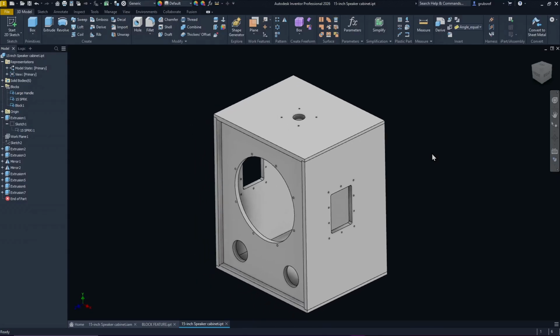And then you have the ability to take a sketch or capture something off something that does not have a sketch or has multiple sketches where you would spend way more time trying to recreate. So that's a simple way to make a sketch block, reuse it, and take it to any model. You can also copy these just like I did the other one into a new model. Just pick, shift, copy, paste into another model, and it makes a block library, and you have those available no matter where you're going.